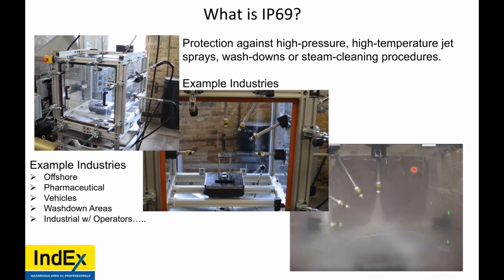This is a consideration that is sometimes forgotten within our industry, but offshore, it's important to get the salt off the equipment. In mining, it's important to get certain chemicals, sludges off of the equipment. So the operator, he doesn't concern himself with IP ratings. So perhaps that's why more offshore users, more industrial users are starting to call for the IP69 rating of their equipment.